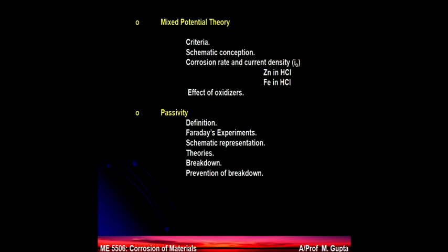So if the cathodic reaction is faster, anodic reaction becomes automatically faster. So in wet corrosion, it is the cathodic reaction which controls the overall rate of corrosion. This is the fundamental design principle in wet corrosion. Minimize or eliminate the cathodic reaction. Anodic reaction will automatically stop.